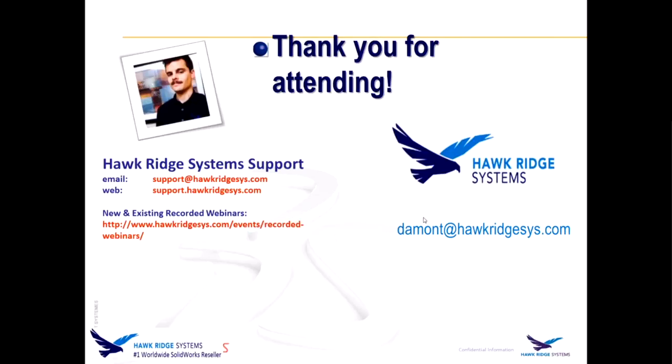Angel's asking, in regards to mechanical components like helical springs, does the software simulate damping behavior based on material properties or on mechanical components? So, Angel, that's a good question. There's actually another method to enter the damping. You can define damping coefficients inside the material definitions in the material library, which means that in any situation, if you use that material on that part, it will use the same damping coefficient. So you can do that.